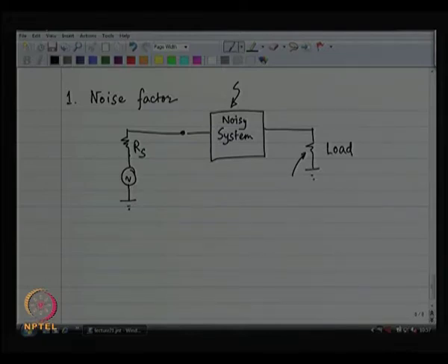You have got to put everything together. So, when you are talking about output noise, you have to take the effect of each of these, sum it up at the output. You talk about input referred noise, you have to take the effect of each of these and find out what should be the voltage that you should have applied to a noiseless system. All right.